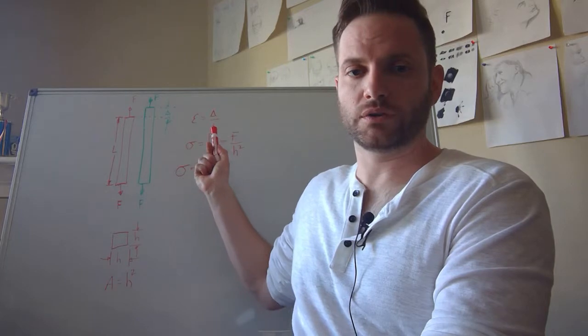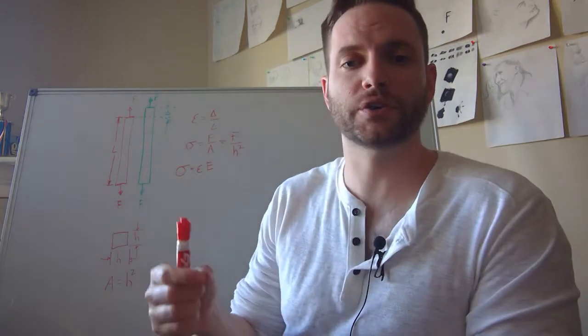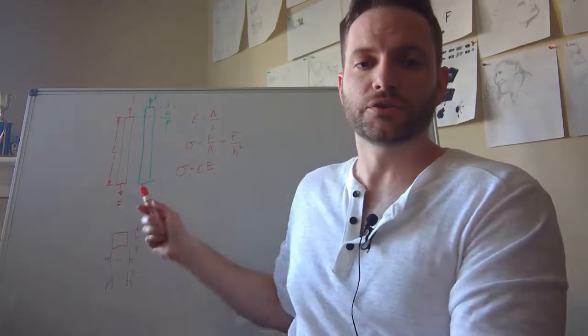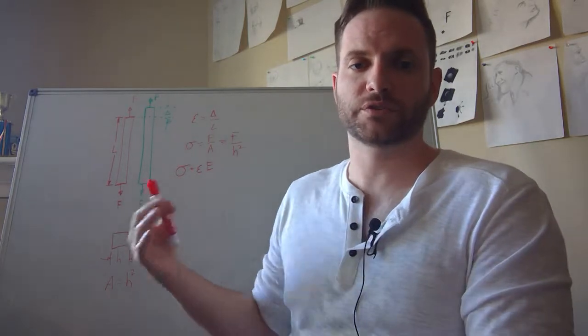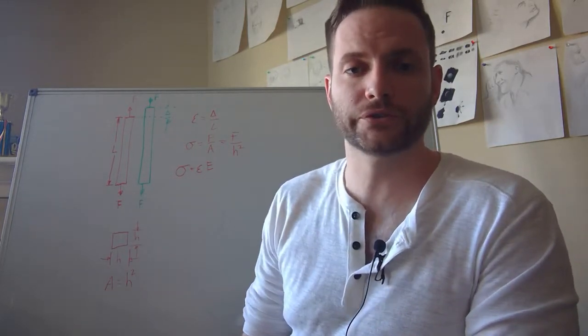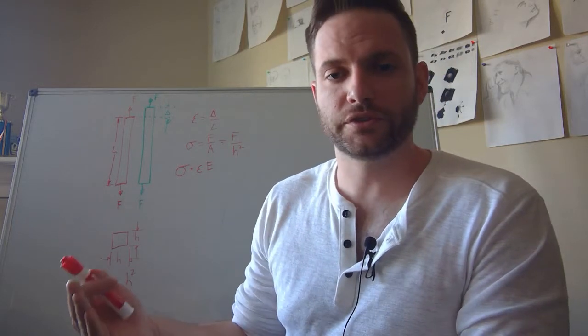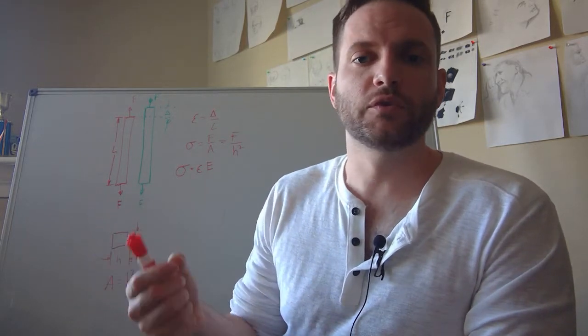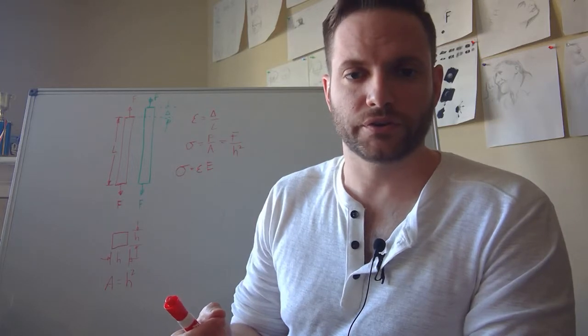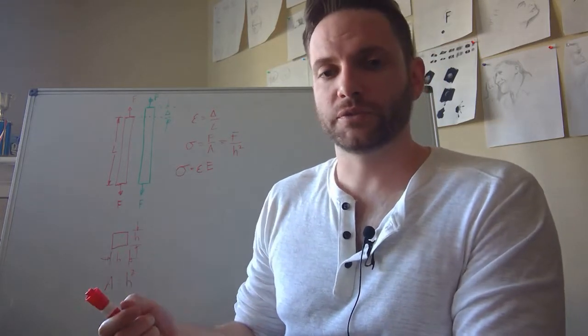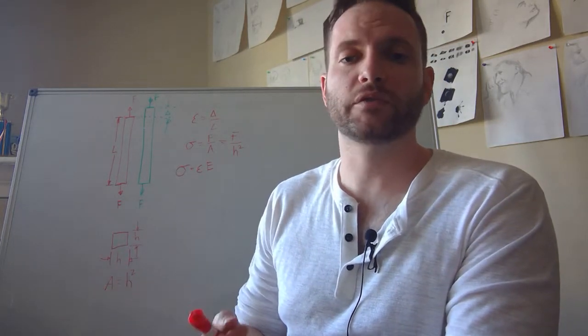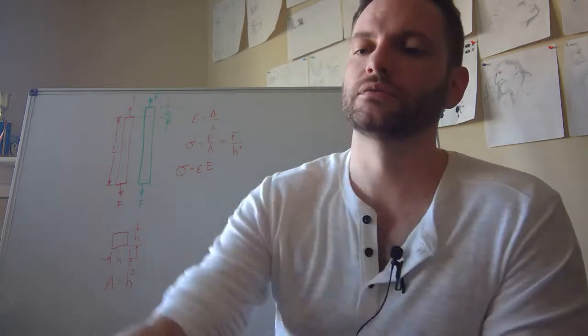So while strain is a measure of how much something changes in length, stress is a representation of how much force that material is under. Stiff materials do not move a lot for the amount of stress they are under. Flexible materials move quite a bit with very little force.